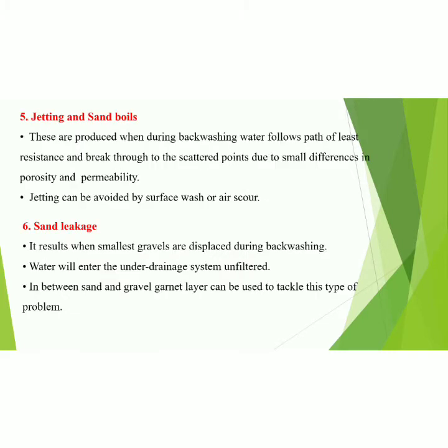Next, jetting and sand boils. These are produced during backwashing. Water flows the path of least resistance and breaks through at scattered points due to small differences in porosity and permeability. Jetting can be avoided by surface wash or air scour.